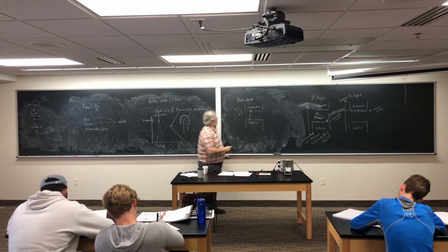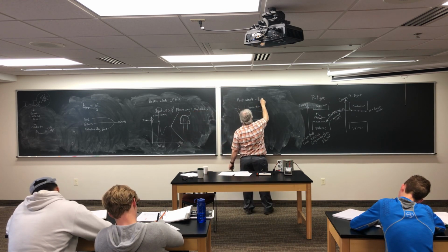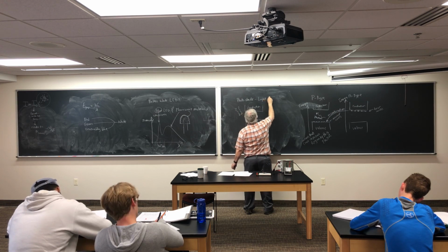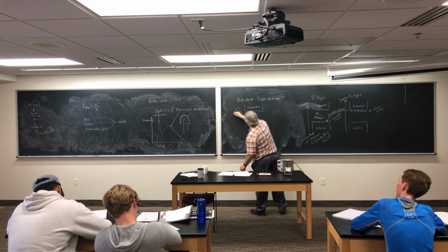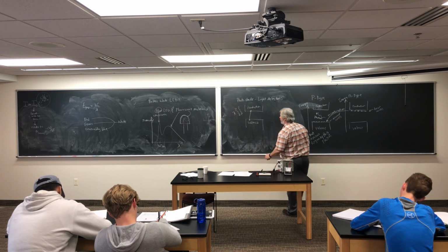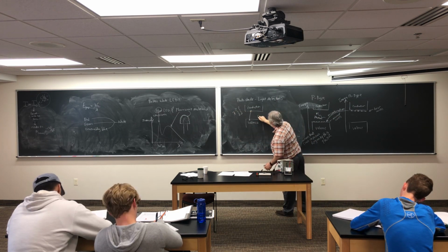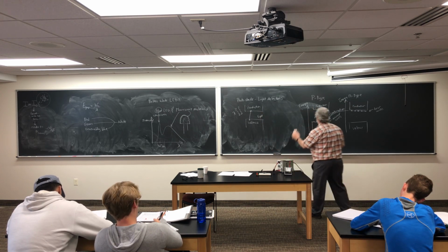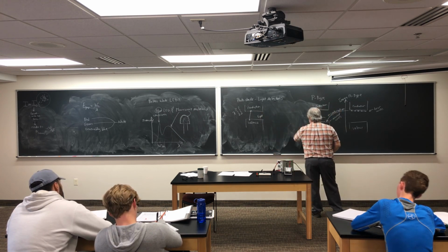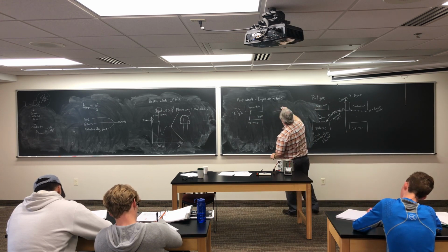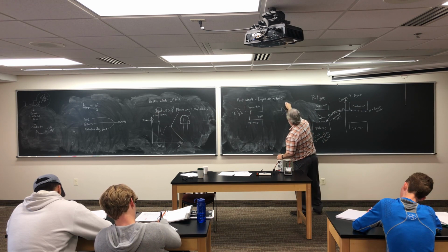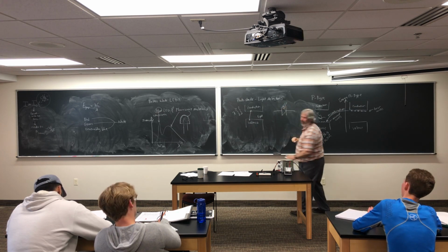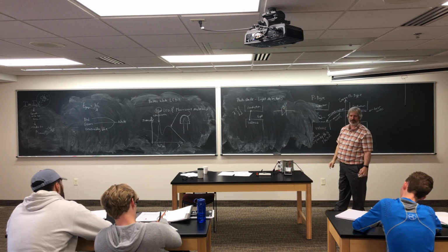Okay. So these are light detectors, and they work at different wavelengths, of course. Your photons at a certain wavelength have to get across the gap. They have to have enough energy to knock electrons up there. And the symbol for this thing looks like this. It's a diode. So it has that symbol, and now you just put the light coming towards it instead of away from it.